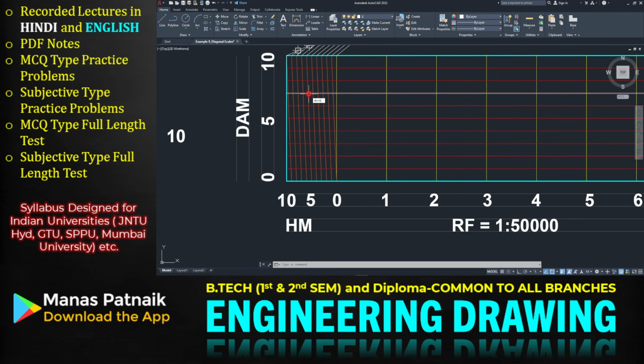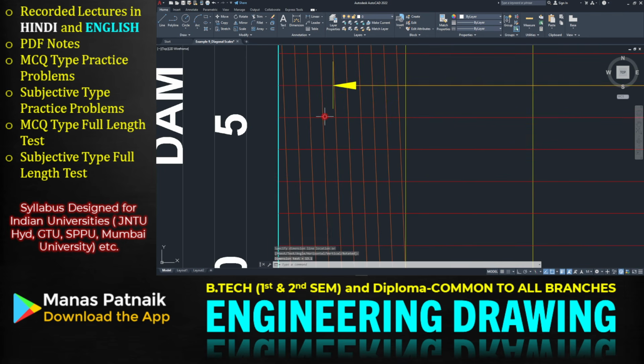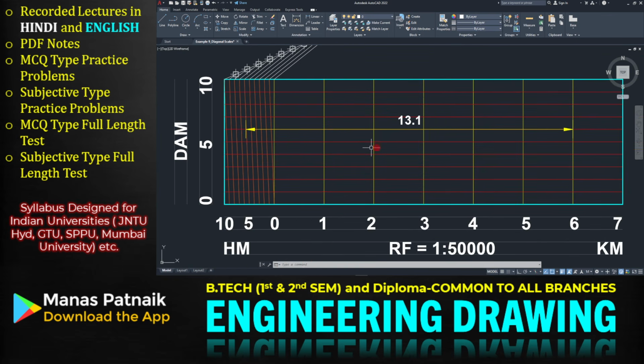So dim linear, enter, click. Where is 6? Here it is. So you can do the dimensioning above, or you can do it simply here. Let me do it here. You have the option of not putting these arrows. You can simply make a point, write A over here, and make a point again, write B. This, by the way, since we are in AutoCAD's environment, is counting in centimeters. However, we know that this is representing 6 kilometer, 5 hectometer, and 7 decameters.